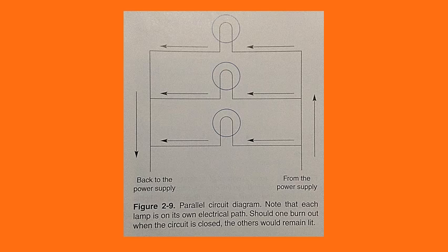Each load is designed to operate at a specific voltage. A voltage rating is given with every device. It is important that the device be operated at its rating. Otherwise, the device can be damaged or even destroyed. In some cases, the entire circuit could be damaged. This is an important reason series circuits are not used in residential wiring.